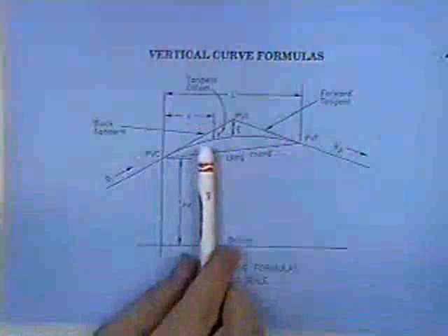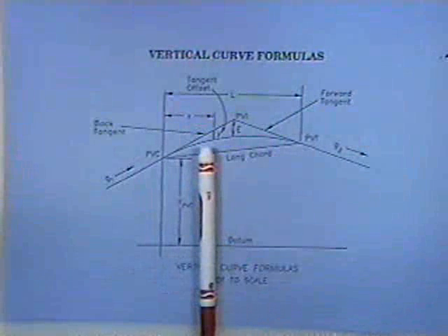vertical curve design. What is important is something that we're calling Y in this particular drawing, or the tangent offset, because we typically can compute what the elevation of that tangent line is, and if we can compute this offset, then we know where the elevation of the roadway surface is going to be. So typically we know the elevation of the tangent, we compute Y. In this case we would subtract Y from the elevation of the tangent to compute the elevation of the roadway surface. Okay.